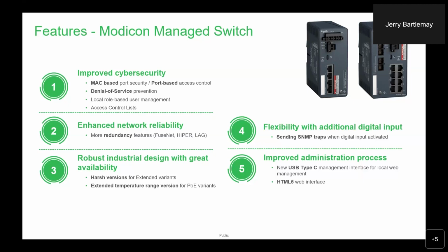Because we use Hirschman, we only provide layer 2 switches. We don't provide layer 3 switches or routers, that type of thing. Hirschman has a full line of those for the industrial market. Anything in the Modicon switch line is fully compatible with anything in the Hirschman line, including the use of HyperRing, which is a Hirschman proprietary ring protocol with very high performance. But some of the newer features of this latest switch line, we've improved the cybersecurity aspects of it. So improved denial of service response and prevention, access control lists.